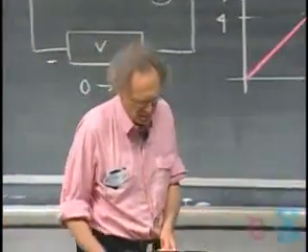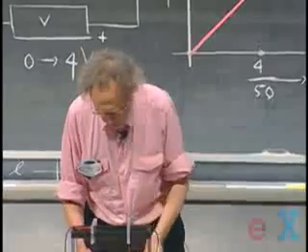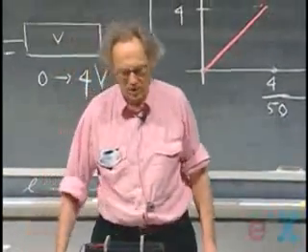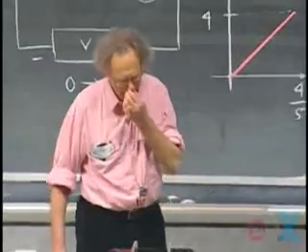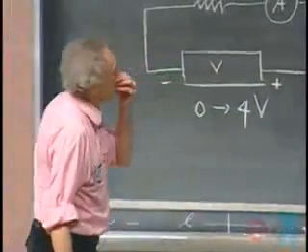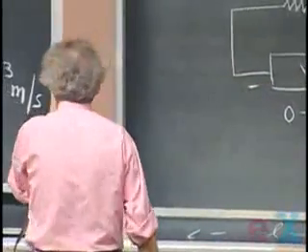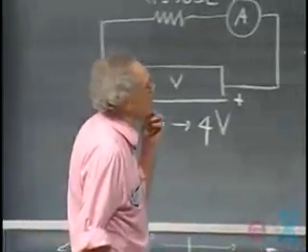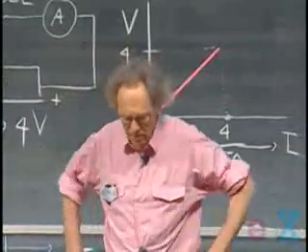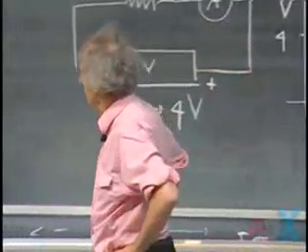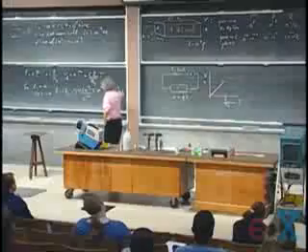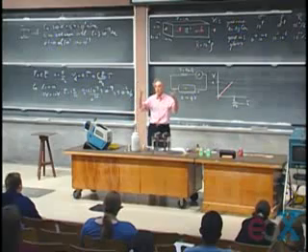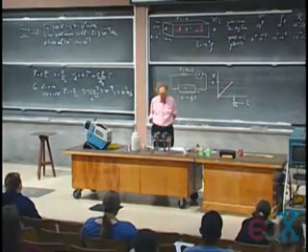So now you may have great confidence in Ohm's law. Don't have any confidence in Ohm's law. The conductivity, sigma, is a strong function of the temperature. If you increase the temperature, then the time tau between collisions goes down because the speed of these free electrons goes up. It's a very strong function of temperature.